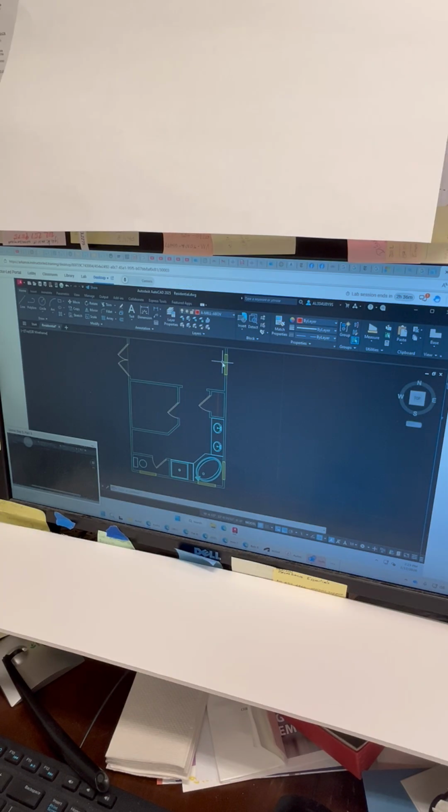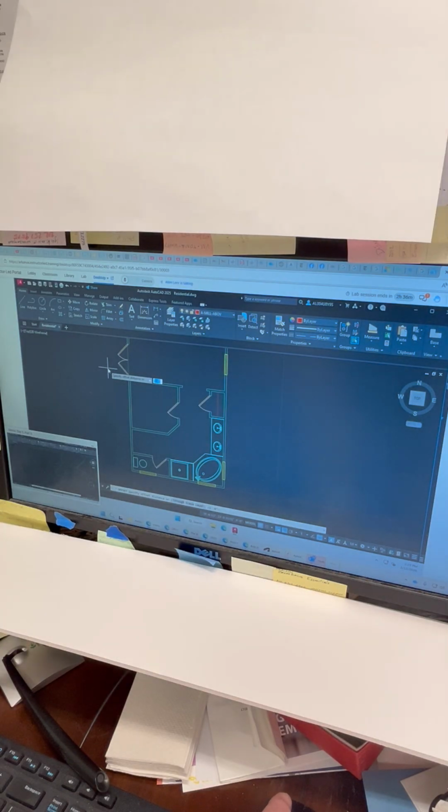Next, start the offset command. Before you enter in the distance, look at the option down here. Layer. Go ahead and click on layer. And notice your two options. You can either keep it as the source layer, or you can have it automatically offset and automatically be on the current layer. So I want everybody to click on current layer, and it's going to automatically offset our lines to be on the A millwork above layer. So change this to current.